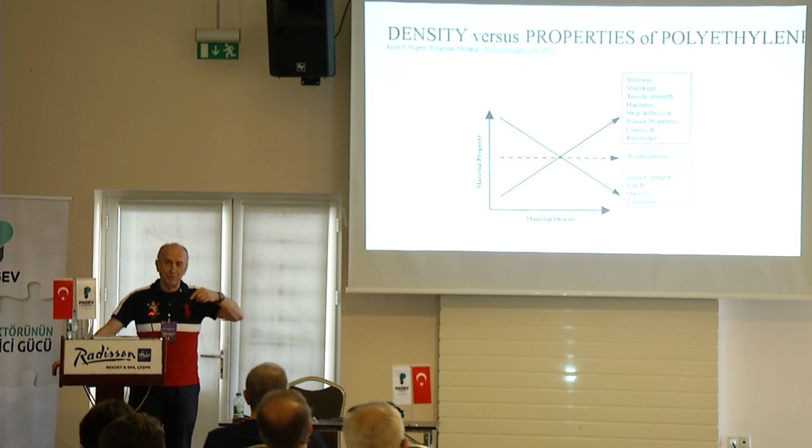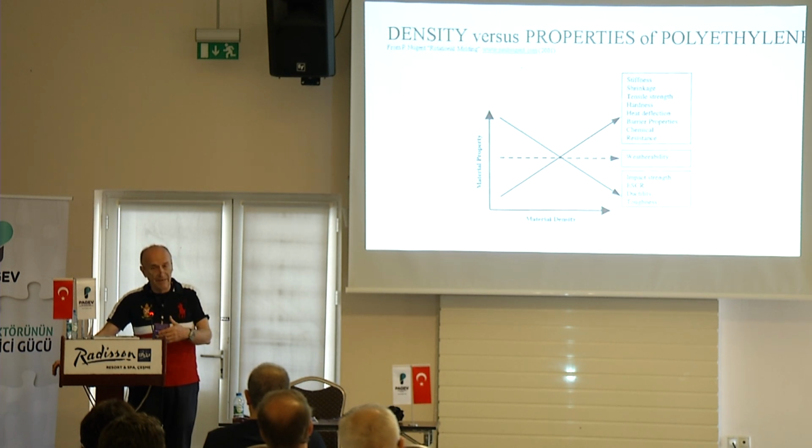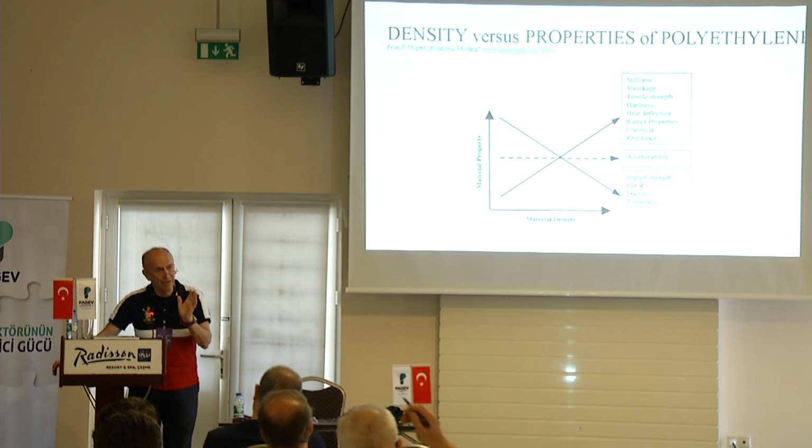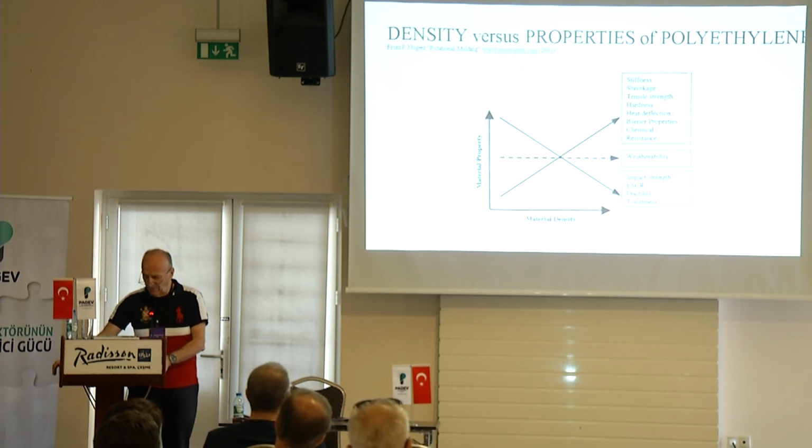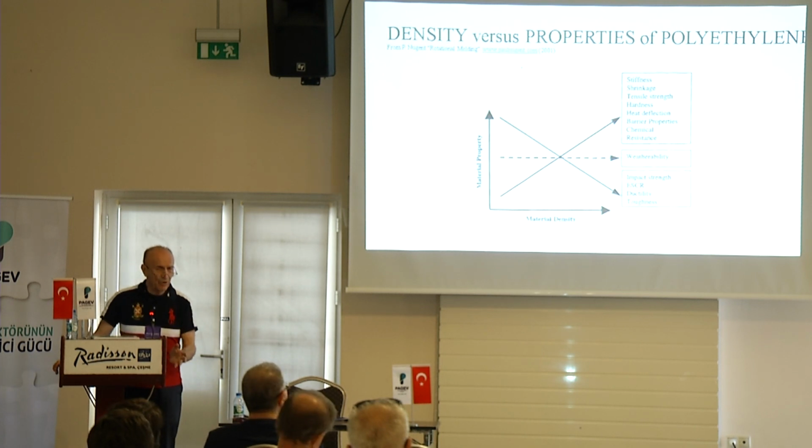In fact, I have a troubleshooting problem where a high density polyethylene was used, and it had more density and it had inferior environmental stress cracking resistance. I think I have a problem also with polycarbonate. I'll show it to you later on. But important properties that you must know and understand.